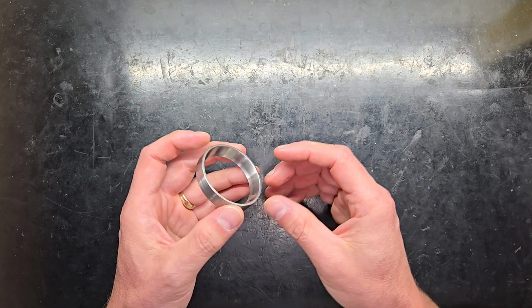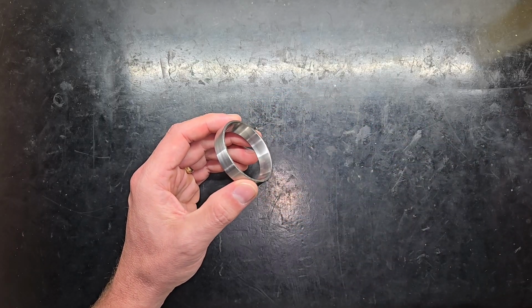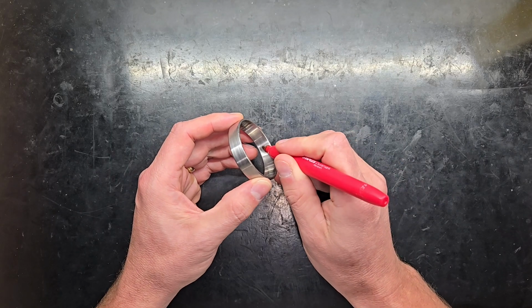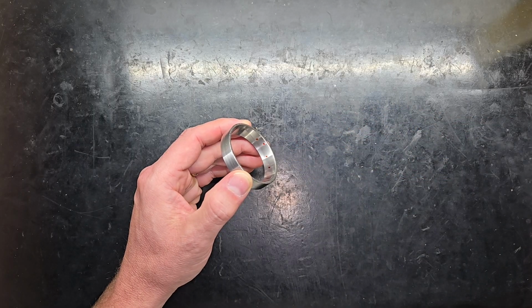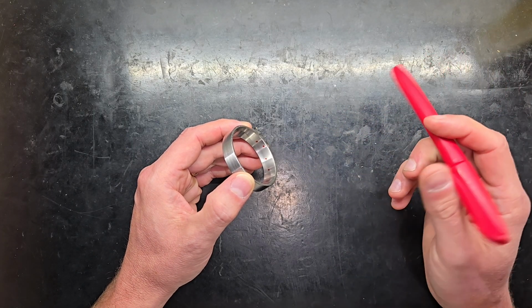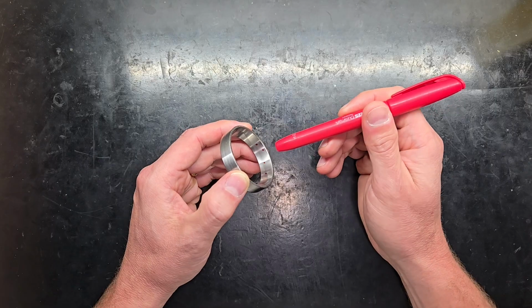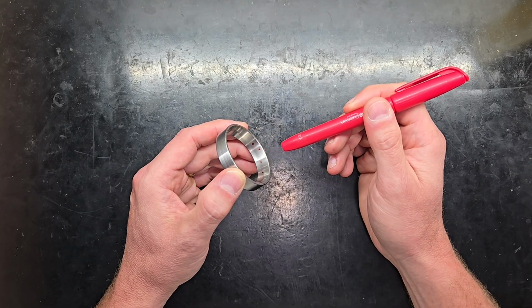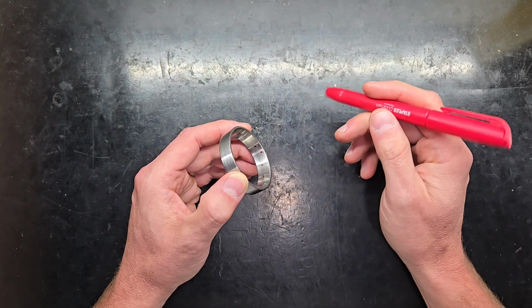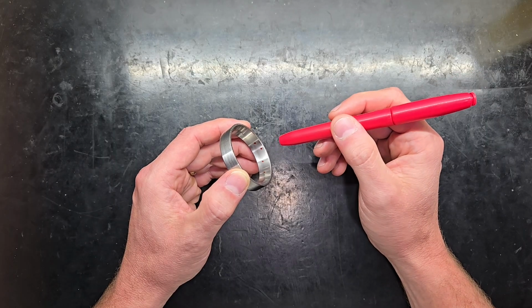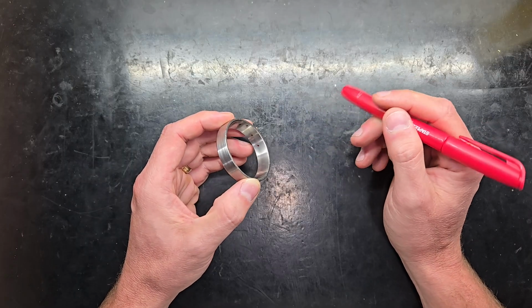Surface fatigue is the last one. Surface fatigue would come up typically in a bearing race, and what you would see are little pit marks on the contact area where the balls or the rollers of the bearing element have been rotating. What causes that are high stresses, and those high stresses are resultants of either discontinuities in the surface of the bearing race or in the matrix of the metal itself. So as that bearing is loaded and as it's rotating, those stresses are exceeded, and then material is removed. It is fatigued from the surface, and that would then show up as pitting in the bearing race.